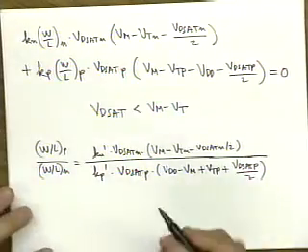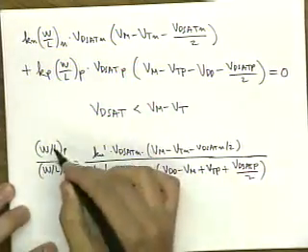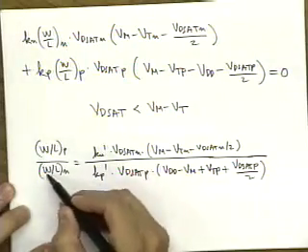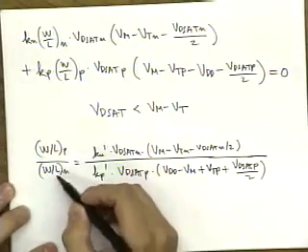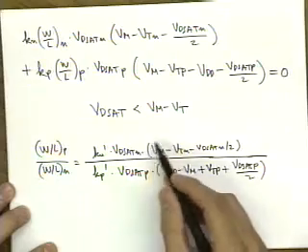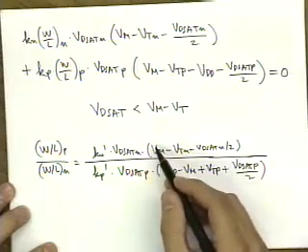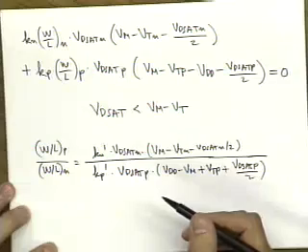And then you can calculate the ratio of Wp over Wn, assuming that they're equal length, for a symmetric voltage transfer characteristic. And then let's plug in some numbers.